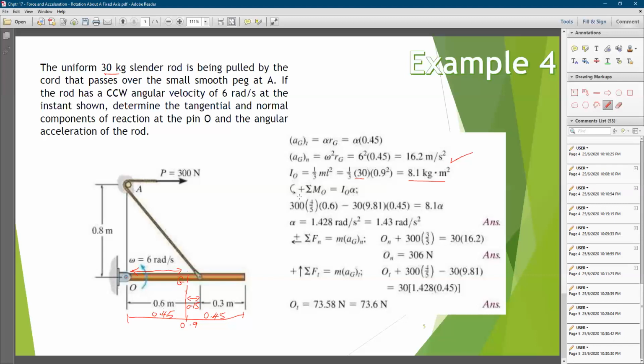Moving on, we want to calculate the summation of moment at point O. Counterclockwise, again, is the positive direction. Then we look into all the forces involved. In this case, if I deduce this pipe here, it is 0.8, and down here is 0.6. This one is 0.8, this one is 0.6, or we can also say 4.